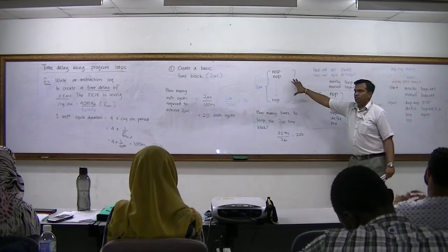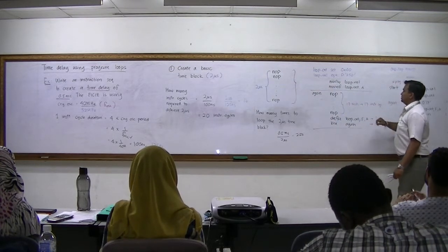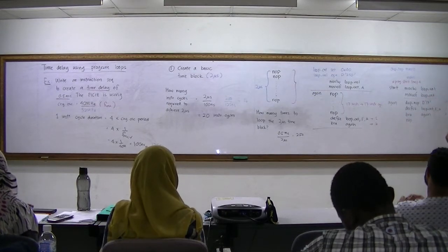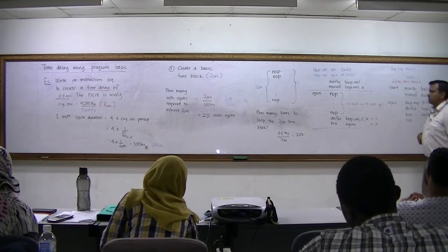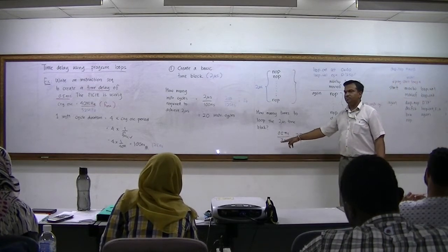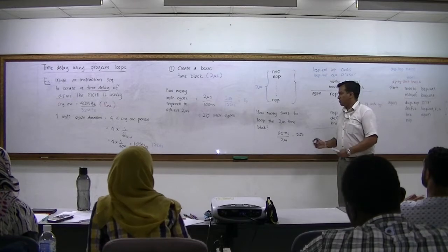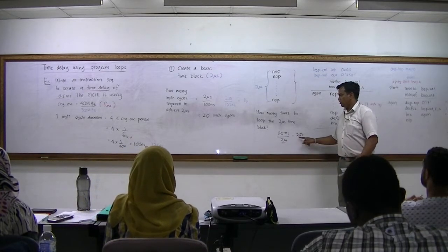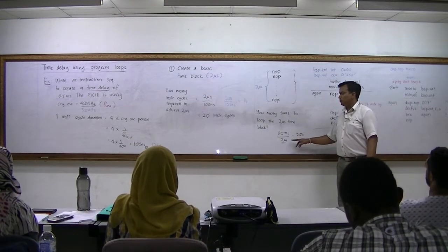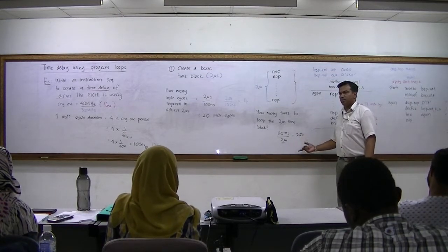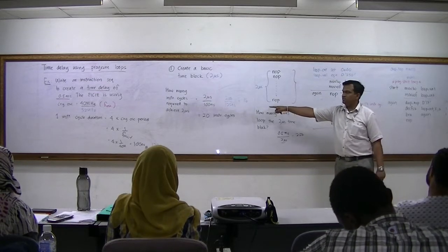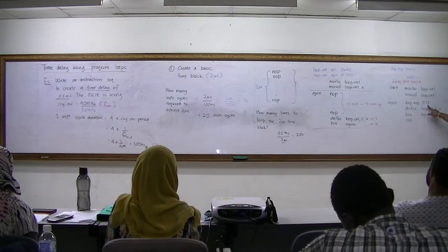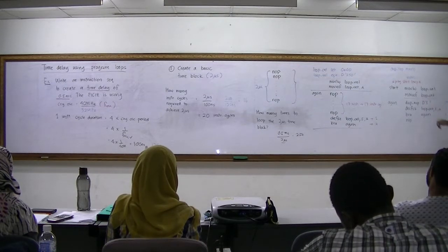So this one I've showed you. This is how we design everything. 17 of these. So what are the things that we need to change here? This is still the same. This one has not changed. Why? Because the basic time block you are still setting to 2 microseconds. So there's no change. You still need to loop that 2 microsecond delay time block for 250 times. But what changed? The instruction cycles required is 16. So what should we write here? Yes, 13. You should write 13.